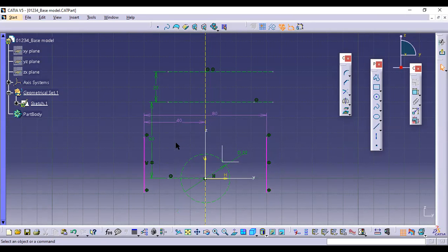Okay, they are not showing anything from the center to this edge. So for constructing this sketch, we need this 40 mm. We use this 40 mm, but as per the drawing, this sketch also should be matched with the drawing, so that when you refer to it tomorrow or after one week, you'll easily come to know, okay, you can match with the dimensions and you can easily find out from where I got this dimension, why I have used this dimension. That's the reason we always need to match the dimensions here in the sketcher with the drawing.